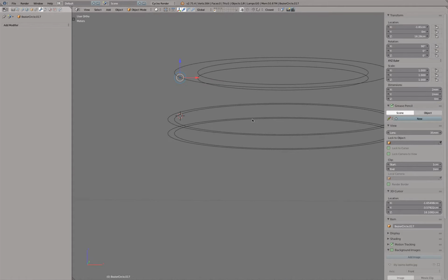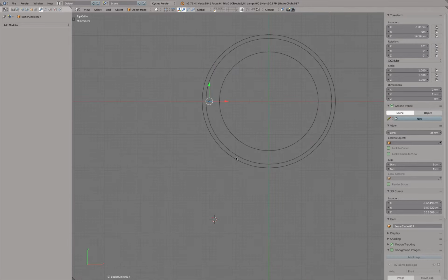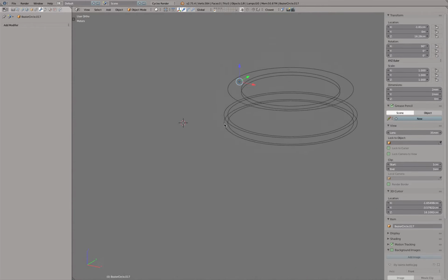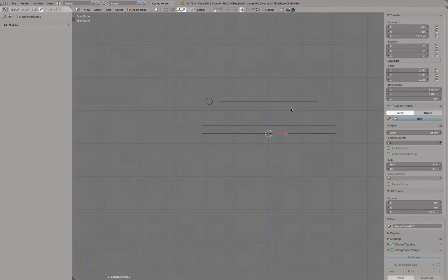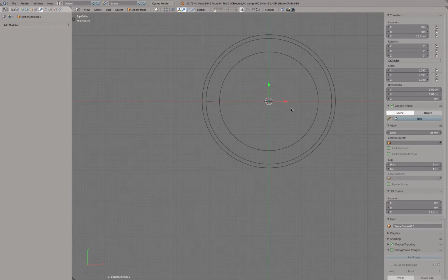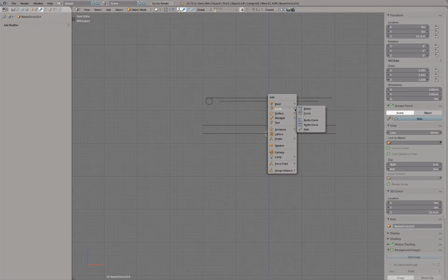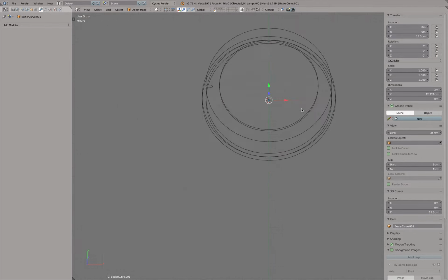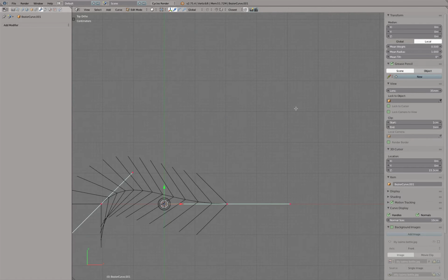Okay. Now, we have to add a new spline node so we could draw a side profile. And that 3D cursor right now you see is misplaced. So what I'm going to do is I select this ring, which is perfectly positioned x and y to 0. Press Shift S, cursor to selected. So you see I have the height and I have x and y perfectly positioned. And then we can go Shift A, curve Bezier, 7, zoom out a little bit, press Tab, and scale everything down.